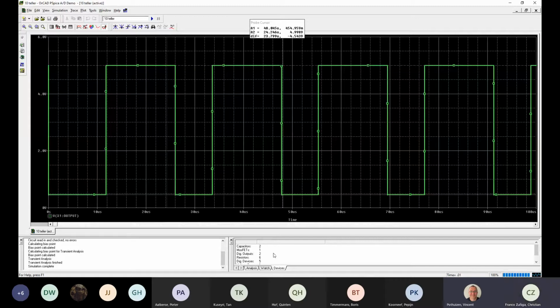Now, going back to the conclusion for this moment, before speaking about the duty cycle, you understand now how you can measure the frequency in PSpice. Yes. So we looked at the difference of time. Yes, so 69 microseconds minus the 48 equals 21 microseconds. Frequency equals 1 divided by the time of the period. So that's 1 divided by 21 microseconds. Did you calculate the frequency? Did you write this down in your Word document?